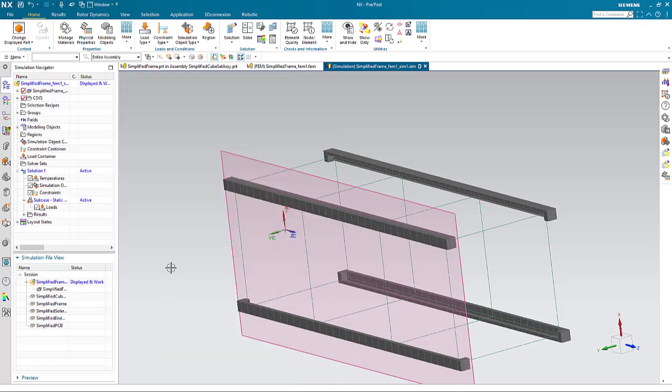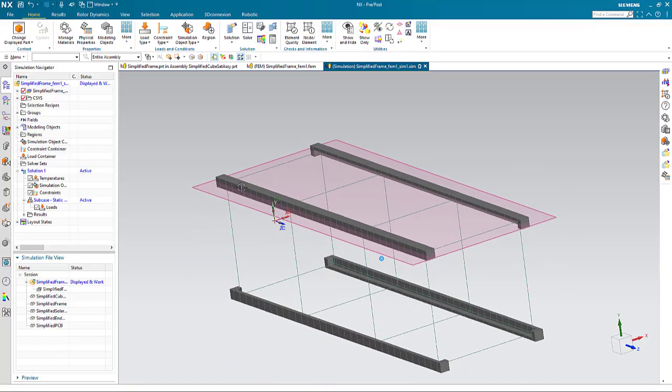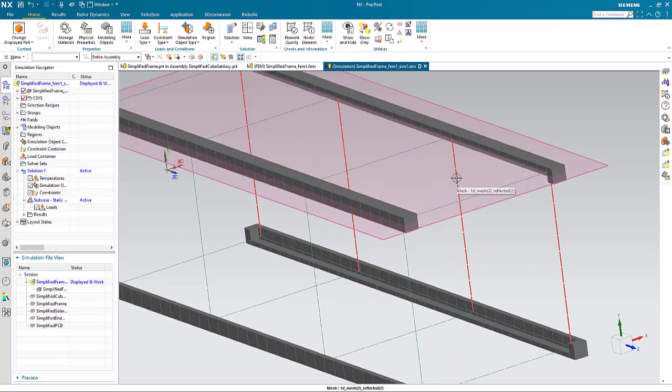Now, the reason why I do this is because when we put together an assembly FEM, we have to create one within this model, this mesh. We need to join all of the surfaces with the corresponding beam elements. Okay, so you can see the beam elements, not these are the rail supports, but the beam elements sort of inside. So we're going to create those together.